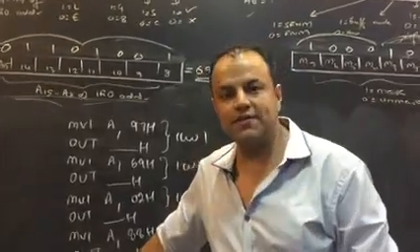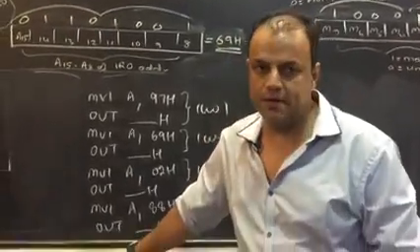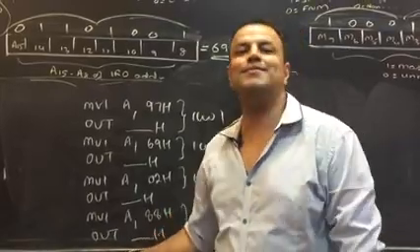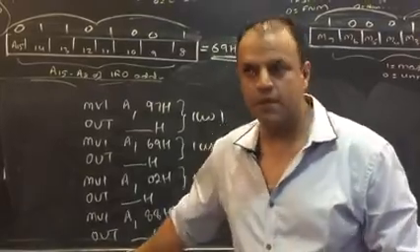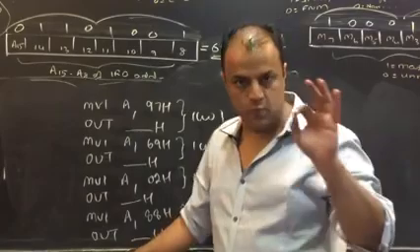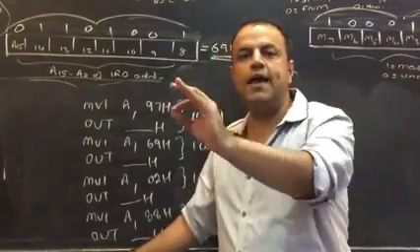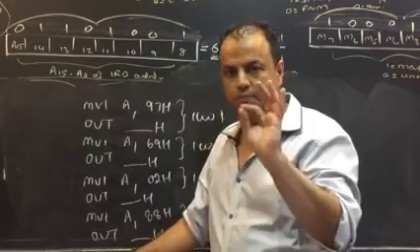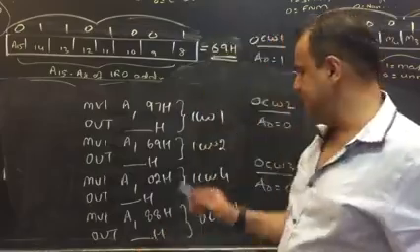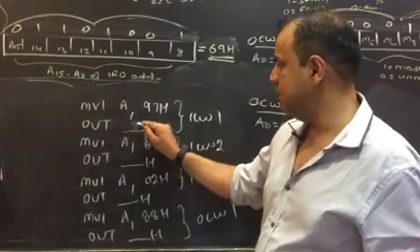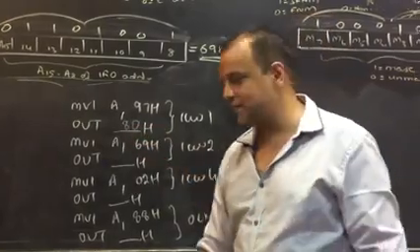Now, since 8259 is an IO device, the address will be an 8-bit address, so you can choose any address you want to. Let's say the address is 80, fine. So clearly write, in very clear words, assume 8259 is at address 80H. Since 8259 is at 80, you will be giving ICW1 obviously at 80H, that's the address of 8259.